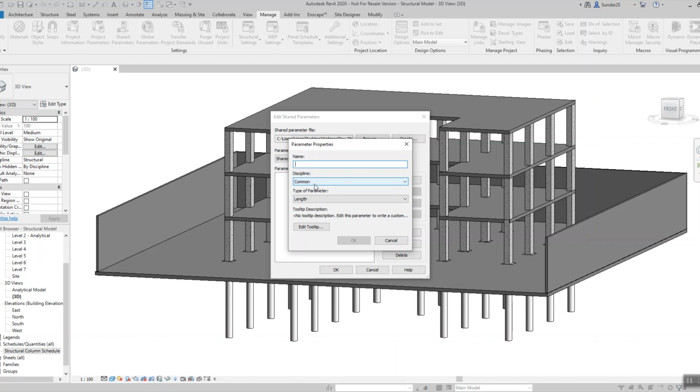So I can create that external wall parameter. External walls all come under this category. It may be a compound wall, it may be an exterior building wall, it may be a facade wall, anything. So for all the walls, I want to apply this parameter. So how to apply this? We'll see now how to do that.